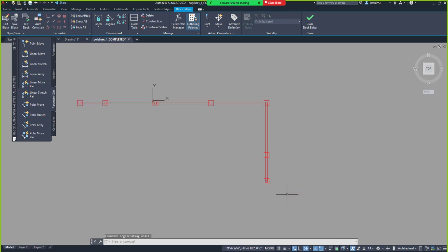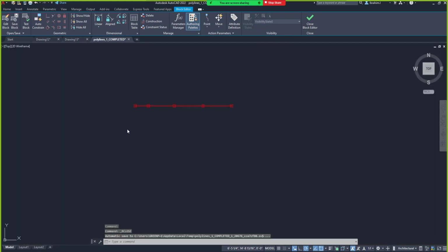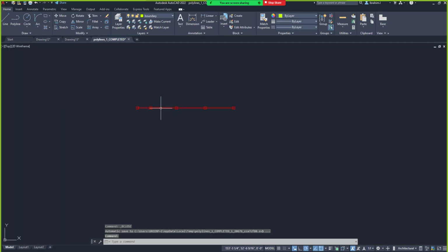Let's say I don't want this other end as well. I just want it to be a straight railing so that when I want to apply it, it's just a straight railing, right? This is what I want. I've made that under edit block. And whenever you are done editing your block, you need to click on what? Save block. And then now click on this other guy to close it. Now this block has been edited, right?